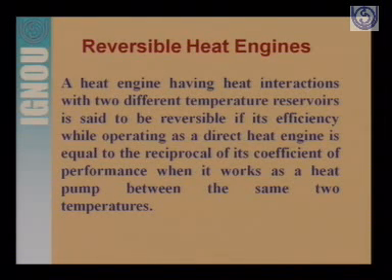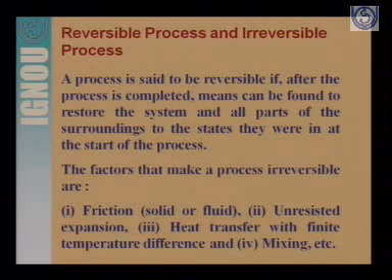So for a reversible heat engine, its efficiency will be equal to the reciprocal of its coefficient of performance when it works as a heat pump between the same two temperatures. You can verify this with the results which we have already discussed for the efficiency of a heat engine and the COP of a heat pump. Now let us talk about reversible and irreversible processes.